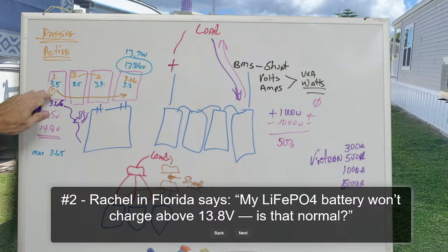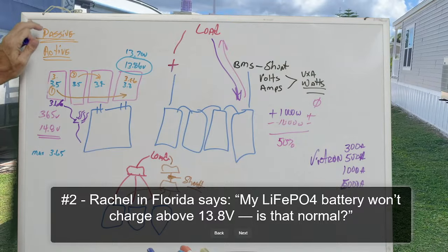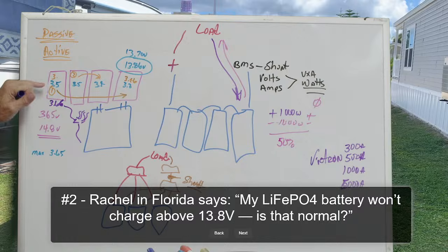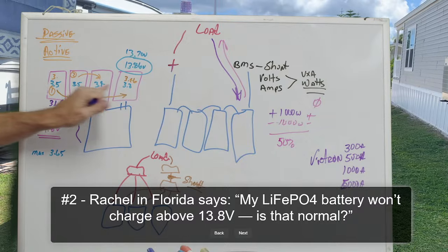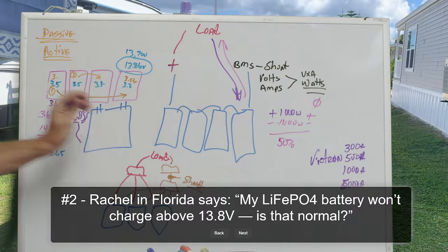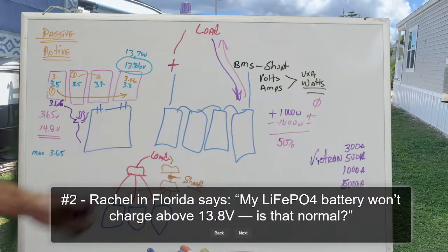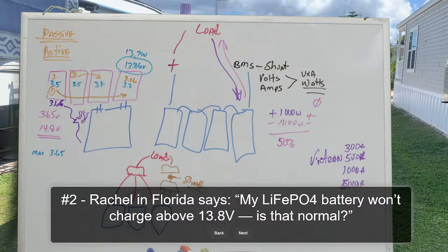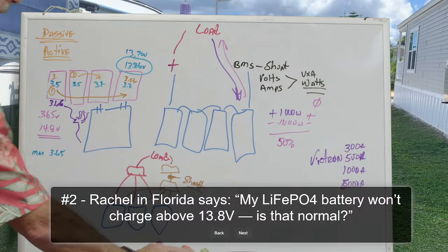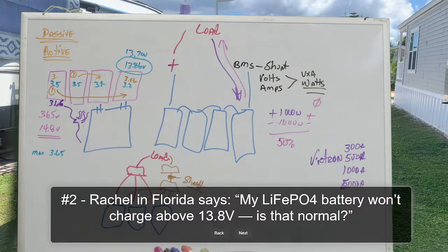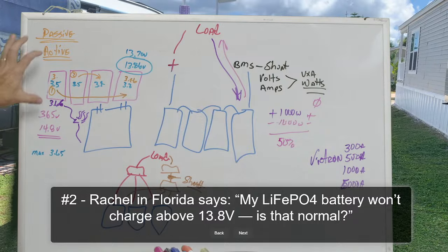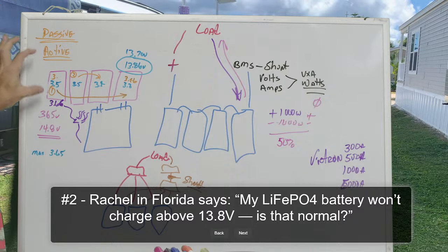But unfortunately, this is not as popular anymore, as the energy here is just wasted and it's not actually transferred from one cell to another. And that is why you've started seeing on the market the difference in the active balancers and the passive balancers to attempt to get the state of charge more under control.